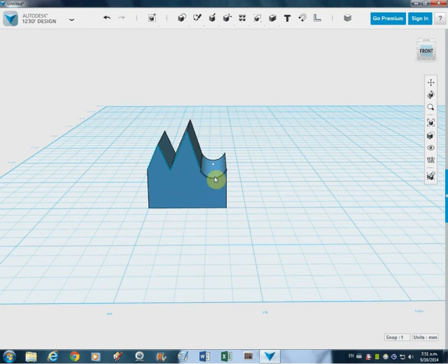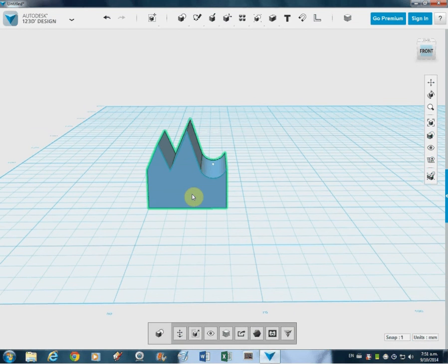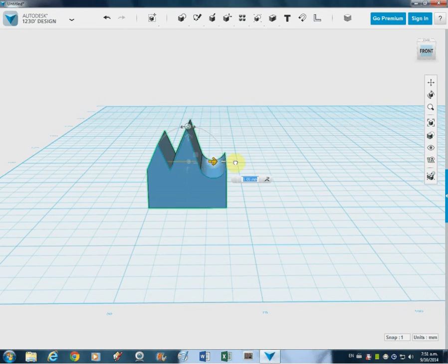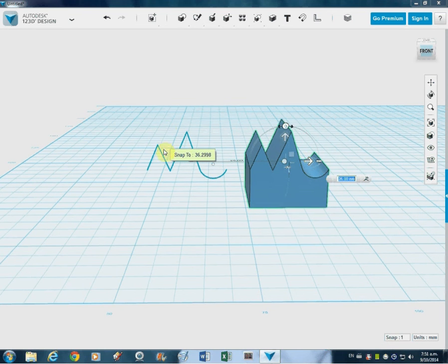One last thing, remember your sketch gets left behind. So if I select this object now, Control T, and push it over there, you're left with the sketch behind it, which could be quite handy because you might want to use it to chop out another piece. So that's that one. That's using Sketch to split a face, which we'll probably do in one of our projects.